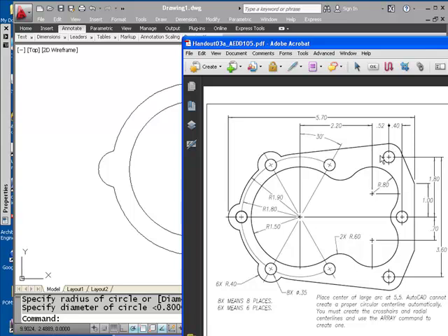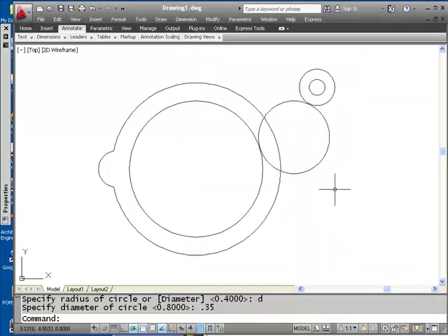Now I'm not using the arc command at all here. Most of the time circle is a better choice than arc, because unless you know the actual endpoints of the arc, it's not really possible to draw it. So we're going to draw circles as though we're using a compass. We'll go trim things back after we find tangency.